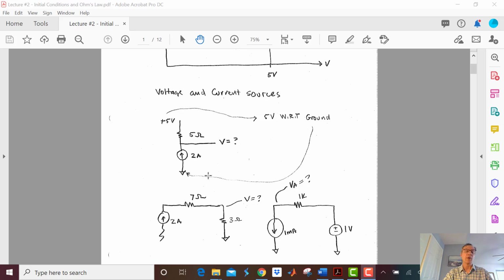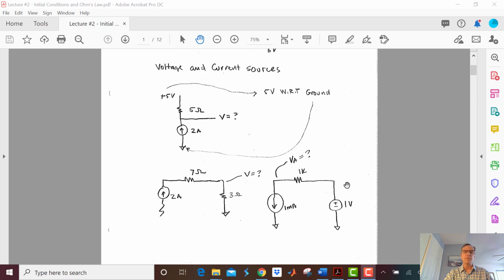You might have an analog ground and a digital ground, but the bottom line is they use the little symbol so they don't have to draw an arrow or a wire every time. For example, if this were a big complicated schematic, I know a lot of things go to ground, and I don't want to have to connect wires between all those grounds, so I'll just use the ground symbol.